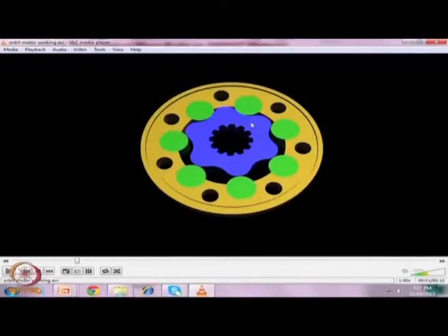If you notice this rotation, you will find that the contact is not up to the full arc, it is some angle, the maximum leaning angle you can say, in both directions from the center. But we can either make it integral or replace this integral part by a roller. The advantage of the roller I have already discussed, which is that we can replace the roller if it is worn out.